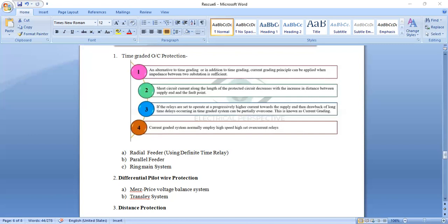Which protection scheme is used for the transmission line? It is the POTT scheme. It is usually used for high voltage line protection against faults in areas with coordination and power stability issues. A three-phase fault is the most severe type of fault that can occur, and fast tripping at high voltages is paramount for personal safety, to avoid equipment destruction and fire also.